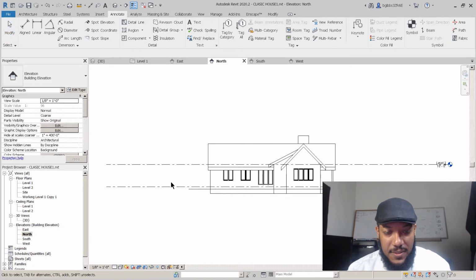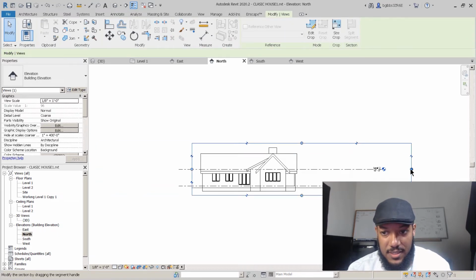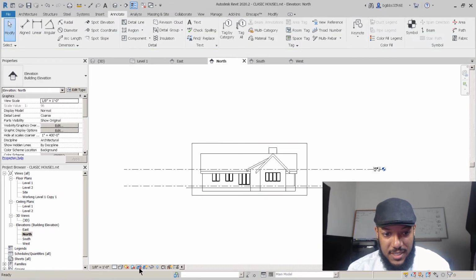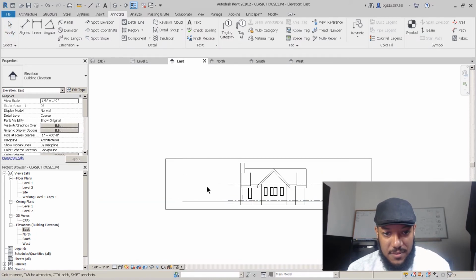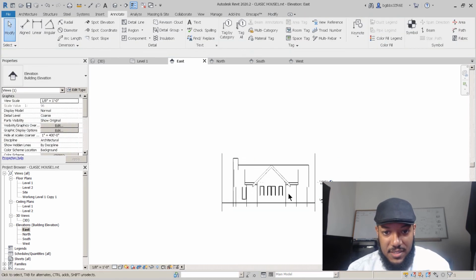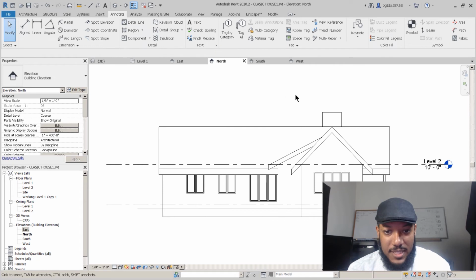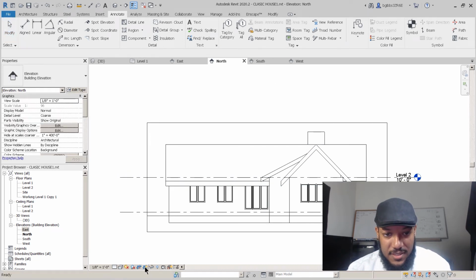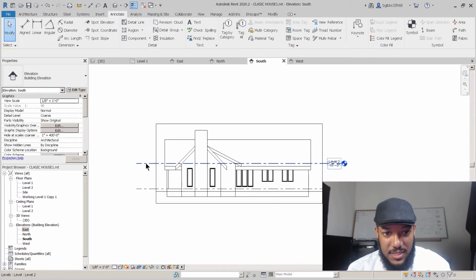We'll do the same thing where we drag it in on both sides. And what we can also do is just go back and hide the crop region after we're finished. We want to show the crop region here. We're just pulling that straight in and put that straight in. So now we have everything in a controlled crop region. We'll double click our middle mouse button to see everything. And we might want to bring our points closer to our little edge for our level, closer to the inside.